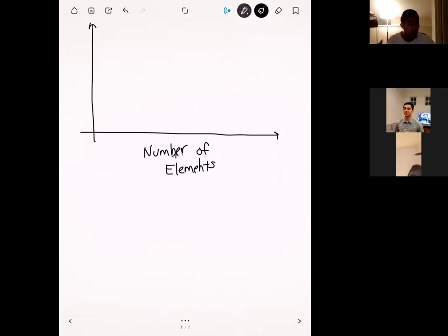And so you can do multiple mesh convergence tests, right? A lot of times you're interested in more than one thing from a finite element simulation, but for each individual graph, you would just pick one quantity of interest. Okay. And so what should happen is, let's say that you start with a very coarse mesh, right? A coarse mesh, we know, should have a small number of elements. So let's say that we start somewhere up here, right?